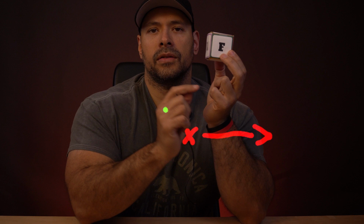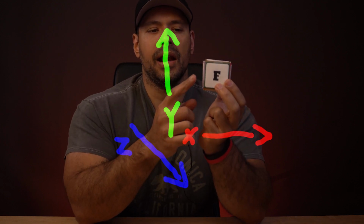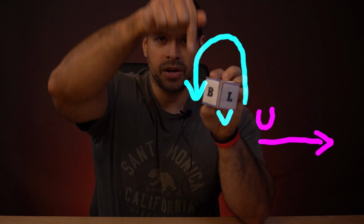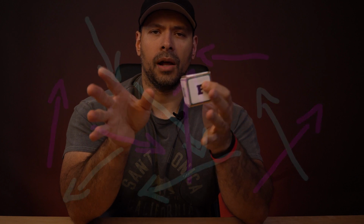But if you think about it, this cube still exists in X, Y, and Z space. But if you look at our UVs, in the front, maybe U goes this way and V goes this way. It goes up. But by the time you get to the back of the shape, V goes down. So since UV directions get all crazy and go in all sorts of different directions, it's helpful to keep them distinct from global or object-based X, Y coordinates.